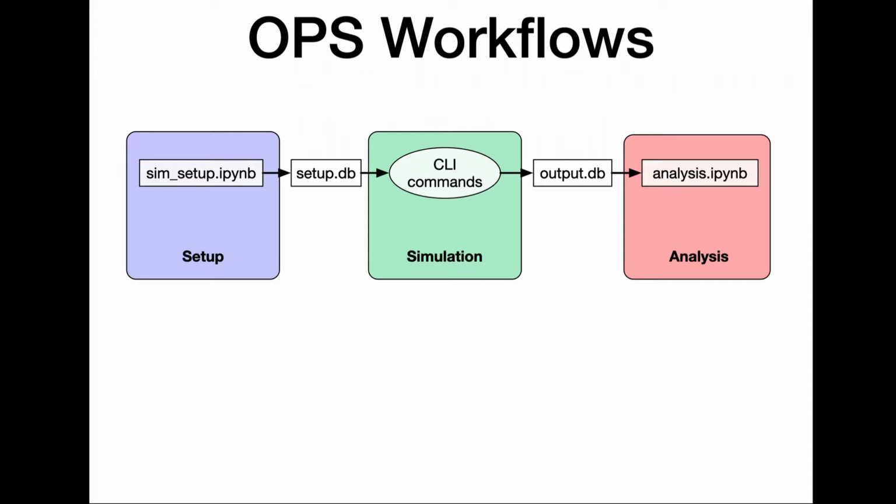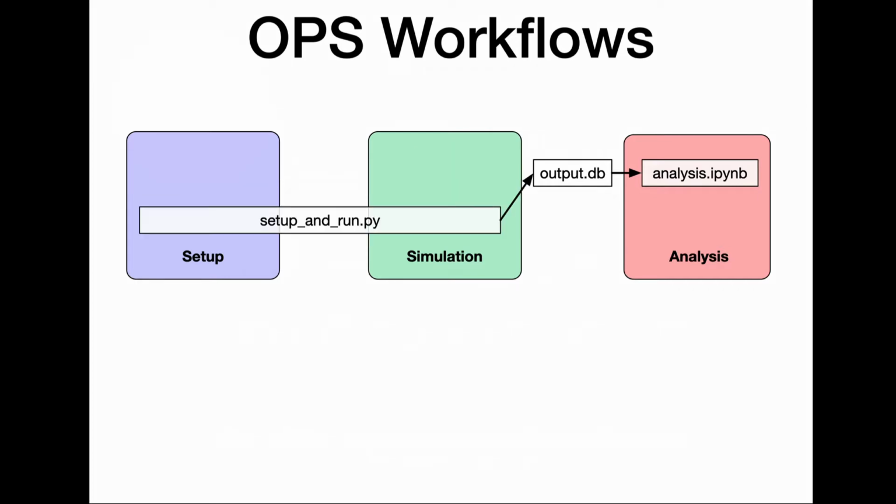Once you have your setup file, you use that as an input to your command line interface commands, which actually run the simulation. This gives you an easy way to run the simulation on a cluster or something like that. The output of that then you will analyze, and typically you do that again in a Jupyter notebook. This is a little bit different from an older approach that we see a lot of people using, and is kind of suggested by some of our earlier documentation, which is to combine this setup and run process into one single script, one Python script that you run.